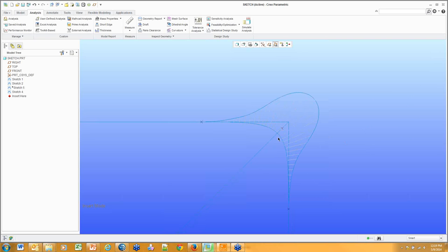This is kind of nice because I can come in here, double-click on the curve, and I can edit all of my points. Okay, so I can kind of move it in, move it out, and see what the curvature looks like. This nice, smooth, flowing curvature here simply means that we do not have a harsh transition between flat and curve. Should this be a standard round, what we would see is a spike, and then a constant curvature, and then a spike, and then flatness again, no curve basically.